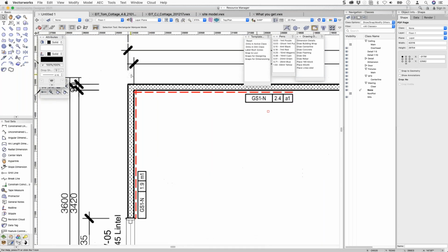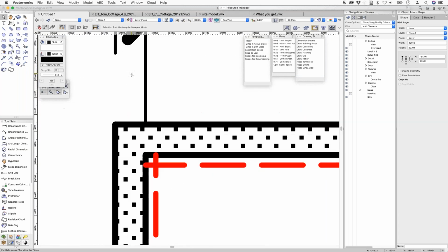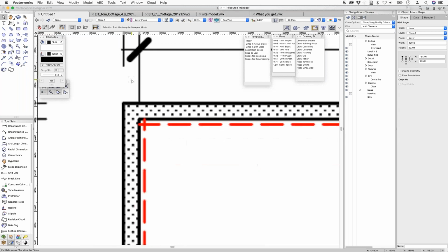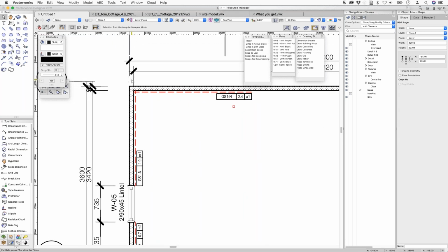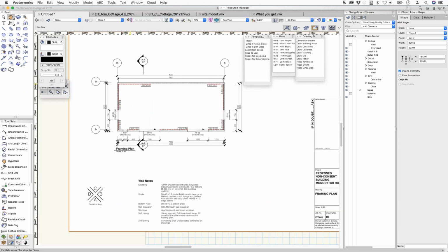And when you zoom into one of those, it goes blurry and it stays blurry, and you end up with these big lumpy blocks, it looks like it's made out of Lego. It's not that nice. If it's a vector-based PDF like this one is, you can turn on the snap to geometry and you can snap to the corners. Notice that it now says endpoint, endpoint. It actually has the ability to snap.